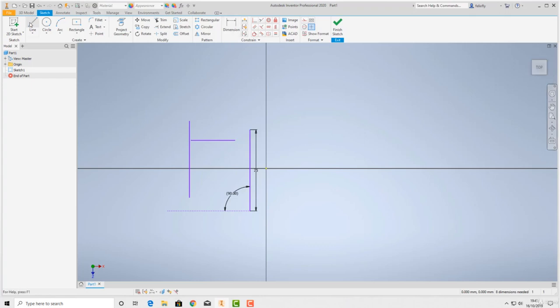Now again, I'll show you by doing, so we're going to draw more lines here. If you want to follow along, just click line, click anywhere in your drawing, for the moment it doesn't really matter. And what we'll do is we're just going to do it by eye. We're just going to go horizontal, okay, so it's 180 degrees, which means we're there.